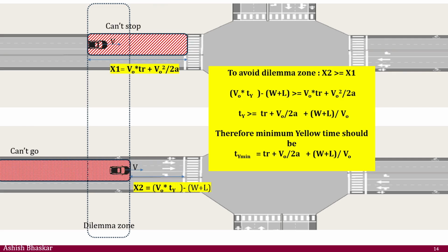So now I have defined the yellow time, and it is different for different intersections. It's not the same. That depends on your design parameters. Whenever you're going to design traffic signals, first you have to understand what that intersection is. You should know the geometry of the intersection. You should know who the end users of that intersection are. And then you start designing it. So I have defined my yellow time. That is one thing I have defined now.